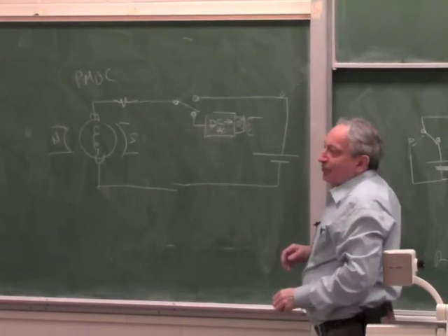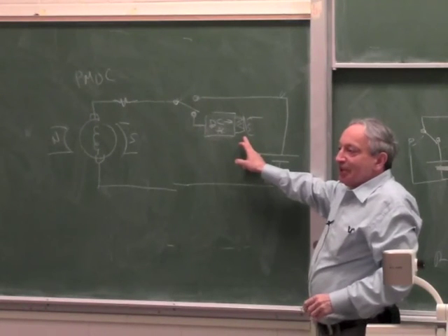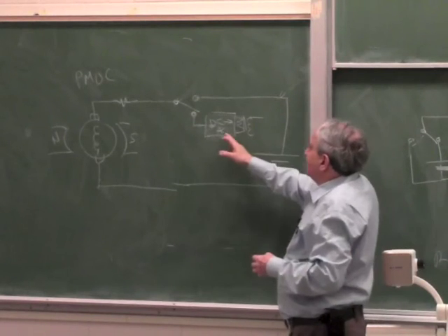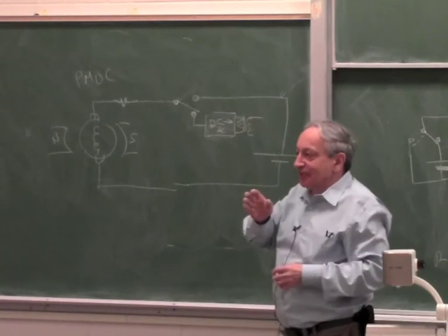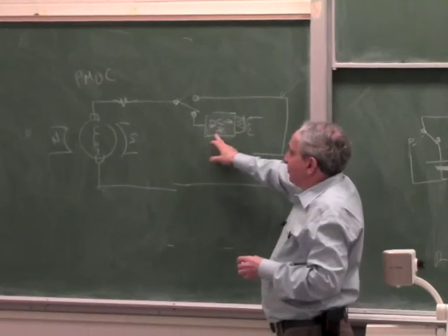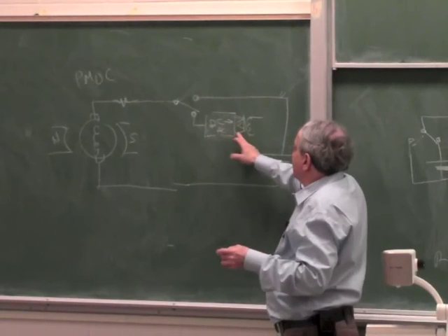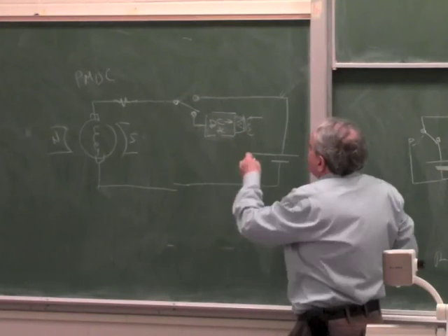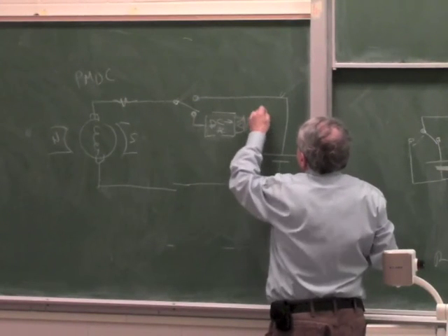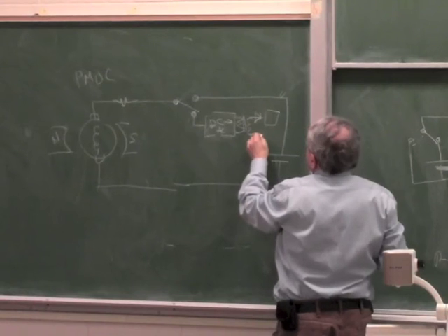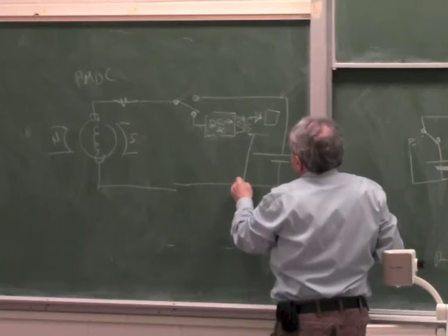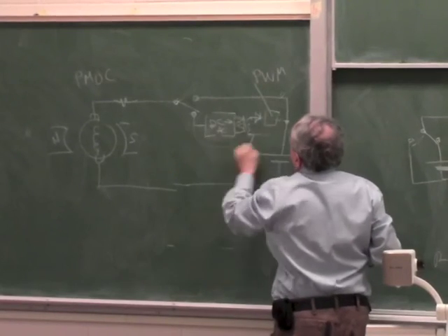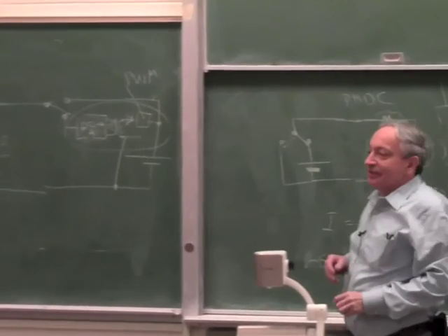So actually, the power supply of your computer has this transformer, mainly for safety, because you want to isolate the line from the output, and also because you don't want to chop at a very low duty cycle. So inside your computer, it takes 140 volt DC, first converts it through a transformer to maybe 20 volt AC. Then it rectifies and PWMs. Okay, then you have a rectifier, then you have the PWM. Okay, and then you connect it to the battery, like this. That's a PWM. So this whole part is exactly like your computer power supply.